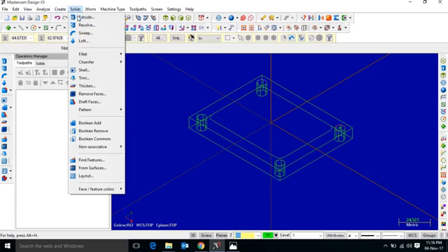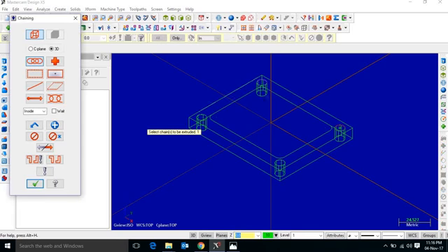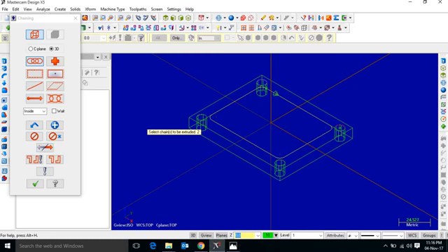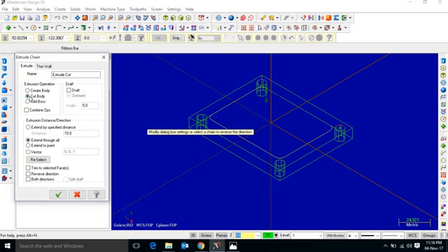Again, solid extrude. Select the entity. We have to pocket this entity up to 5 mm as given in the example. This is the pocket, just 5 mm. Okay, so we are going to the Mastercam software. We already selected the entity, click OK, cut body, extended by a specified distance. It is just 5 mm. Okay, so we enter the file.